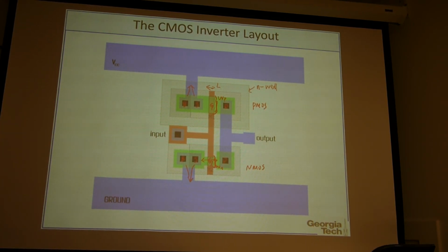So the only thing you can change is the W of the NMOS and PMOS. And you need to adjust that based on the mobility ratio in this technology node. Of course, different technology nodes are different, like 65 nanometer versus today's 10 nanometer or 7 nanometer, so that ratio may be a little bit different. So you need to fine tune this.